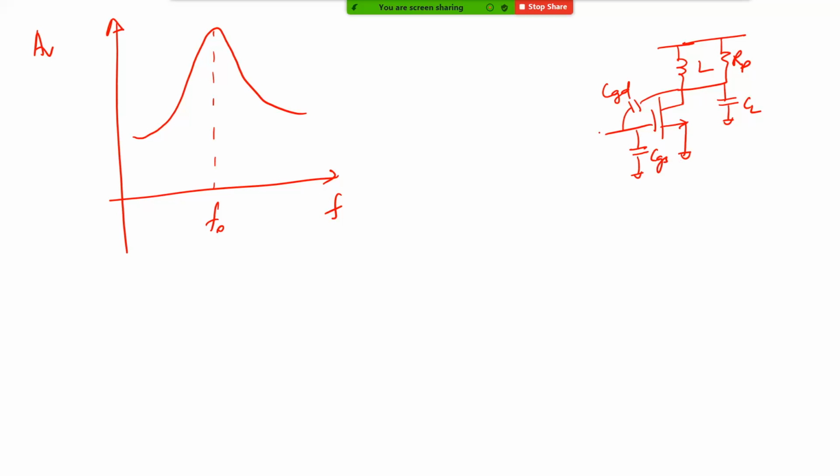If you take a device which looks like this, what is its input impedance? In the last class we took a resistive load and computed the input impedance and we had a very big term. We said that this big term is quite high, and therefore we thought we'll put a resistor at the input, Rp, which is 50 ohm, and then try to design an LNA.